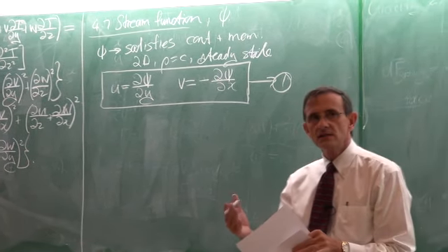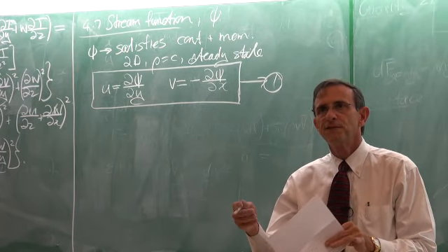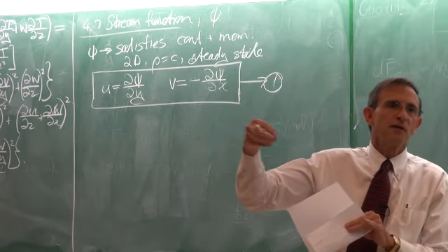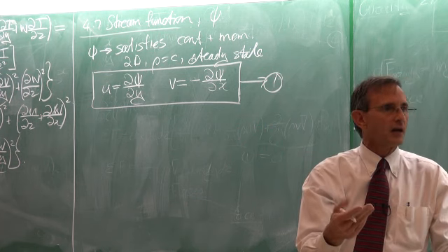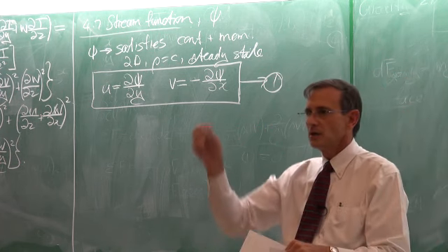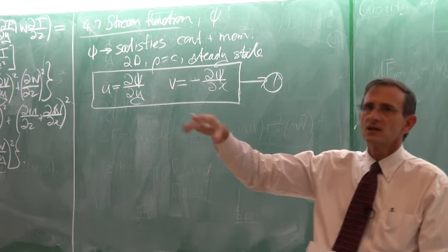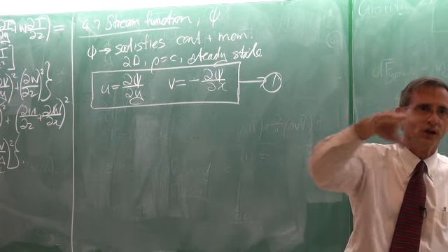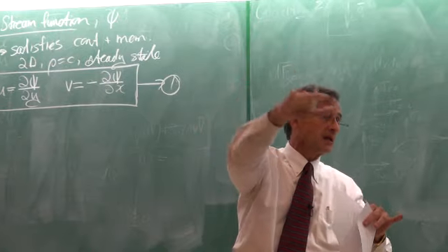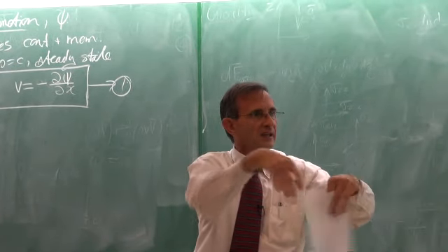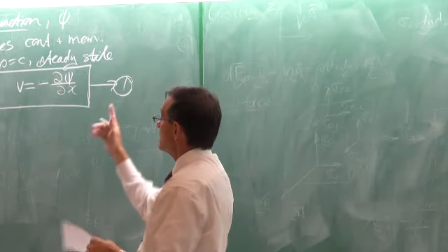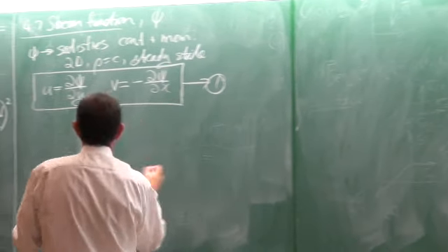Okay. It sort of represents the behavior of a flow particle around a body. In wind tunnel experiments, you've seen it many times. You know, smoke is being generated, and when the smoke is being generated around a body, you can sort of understand or see how the flow would behave. And that is exactly what a stream function is, or a streamline.